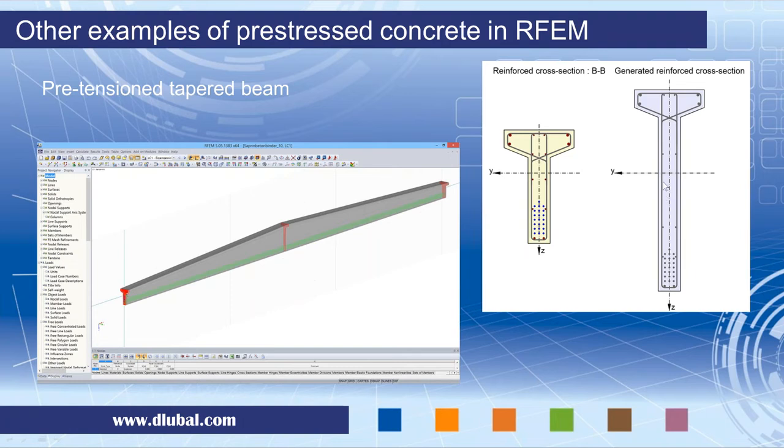So in fact, if you use the templates of the reinforcement, then the reinforcement is adapted automatically along the length based on the calculated depth of the cross-section.